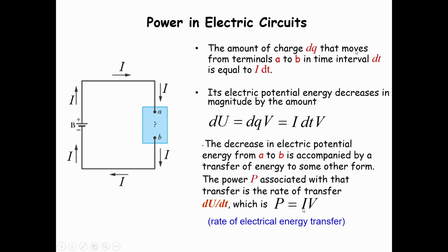In a lot of situations, when you're talking about the amount of energy that's dissipated through a resistor, such as here, you usually want to write this as I squared times the resistance. That's the same thing, right? V is equal to IR, that's Ohm's law. A lot of times that's referred to as ohmic losses. The amount of power generated by a power supply is typically written as VI or IV. They're equivalent, but in some ways they're not.